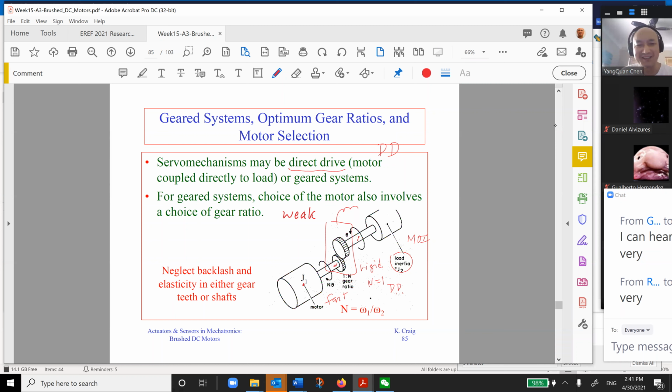This small teeth here, you can break it. Then you can hear the gearbox becomes noisy and noisier. So it's better not to have this one. That kind of drive is called direct drive. Direct drive is much harder to control, and so we'll see why we need a gear ratio.